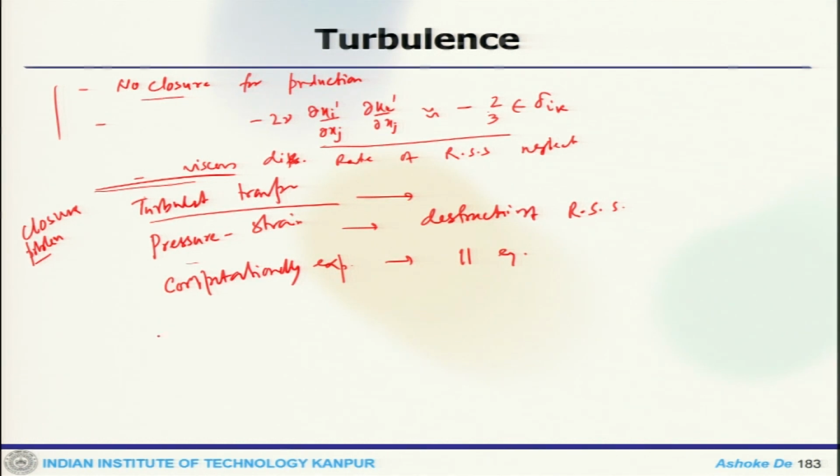Now, an important thing is that one can use this Reynolds stress model when turbulence is strongly non-local. For example, if you have a strong swirling flow or recirculating flow in the presence of the mean flow. In those cases this RSM model is superior to all these two-equation models and so on. Now, that is a RANS based situation.